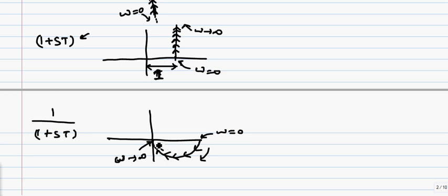And we have seen certain points where the maximum value of this on the imaginary axis will happen when the phase angle is minus 45 degrees, and the magnitude of this point will be 1 by 2, and if you look at the real axis, it will be 1 by 2, and if you recollect, this magnitude will be 1 when omega equals to 0.